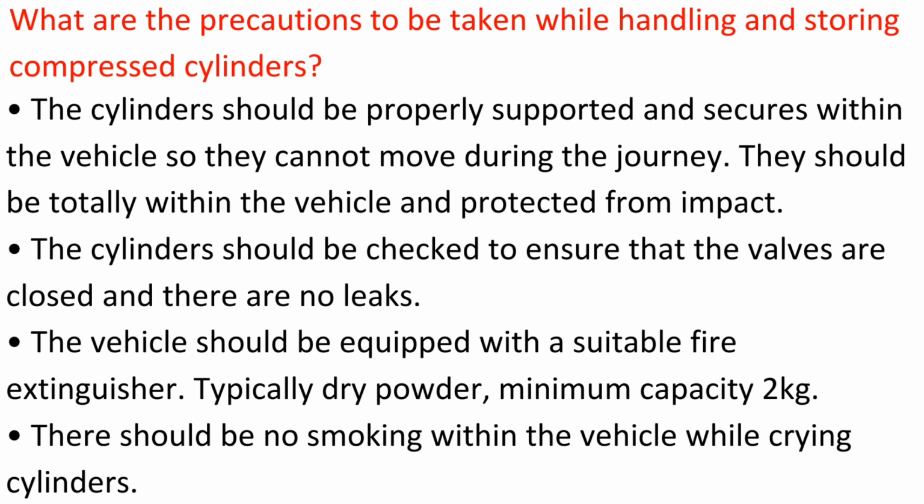The cylinders should be checked to ensure that the valves are closed and there are no leaks. The vehicle should be equipped with a suitable fire extinguisher, typically dry powder, minimum capacity 2 kilograms. There should be no smoking within the vehicle while carrying cylinders.